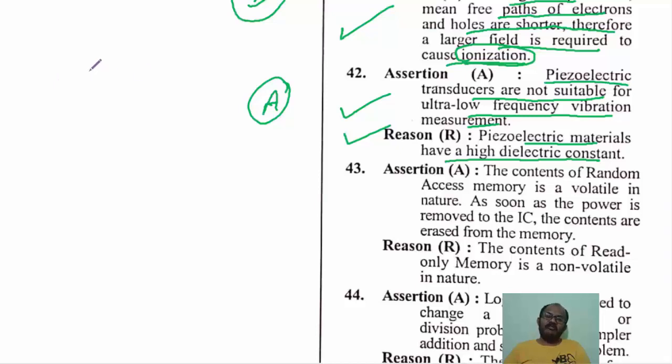Let us know what you mean by piezoelectric effect. For the quartz crystal, I am going to apply voltage across this quartz crystal. What this crystal will be doing is it is going to vibrate at its resonant frequency. If I vibrate this material, I will be getting voltage. So this is what I mean by piezoelectric effect. Supply voltage, it will vibrate, or vibrate that material, you will be getting the voltage. So in the case of mobile phones or electronic gadgets, in order to generate clock pulses, we are going to make use of quartz crystal.